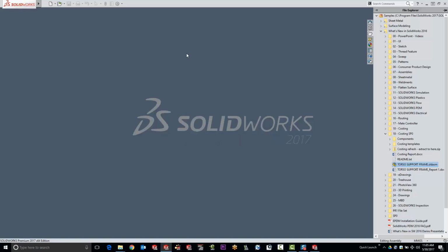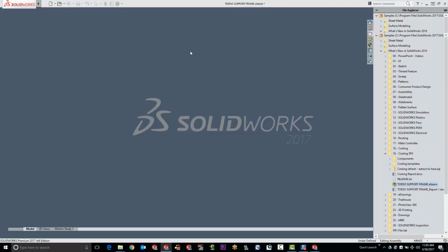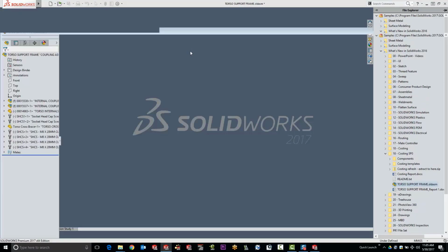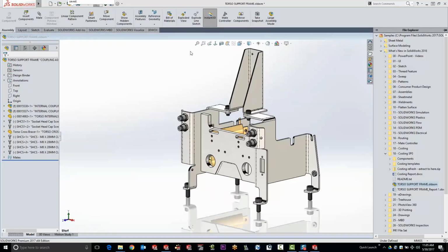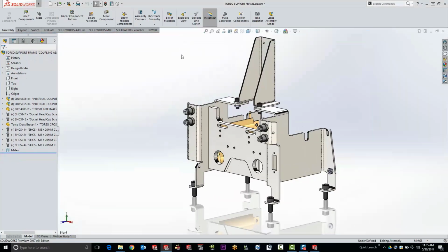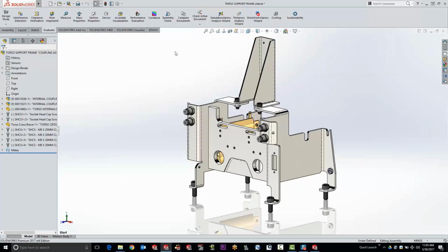If you're then running any costing operations, you'll simply have the part in your SOLIDWORKS interface. SOLIDWORKS Premium allows for costing from the assembly level, and it would individually cost every specific part based on its default material types. When we hit the Evaluate button, we launch SOLIDWORKS Costing. And in this case, it's going to give me a list of my assembly costing templates.